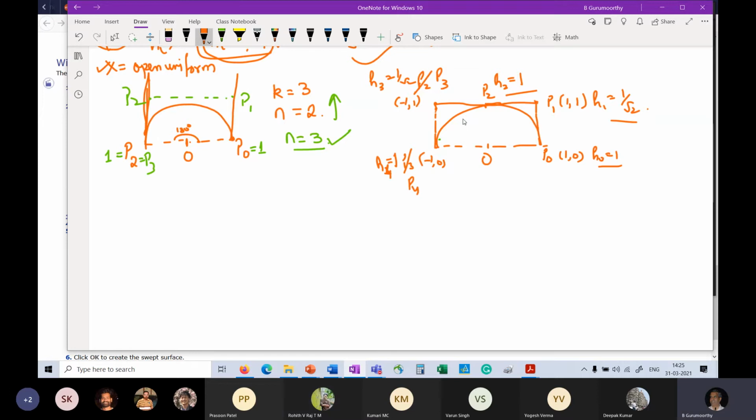That we have basically tried to represent the semicircle, not by some single entity like we tried earlier, but as 2 segments. One segment which is a quadrant, a 90-degree arc of a circle, for which I have already calculated the control points and the weights, so I know what these are. And I just use the same for the next set of control points for the semicircle that I derived, and this gives me this part of the semicircle, and put together, I get the whole semicircle. Correct?